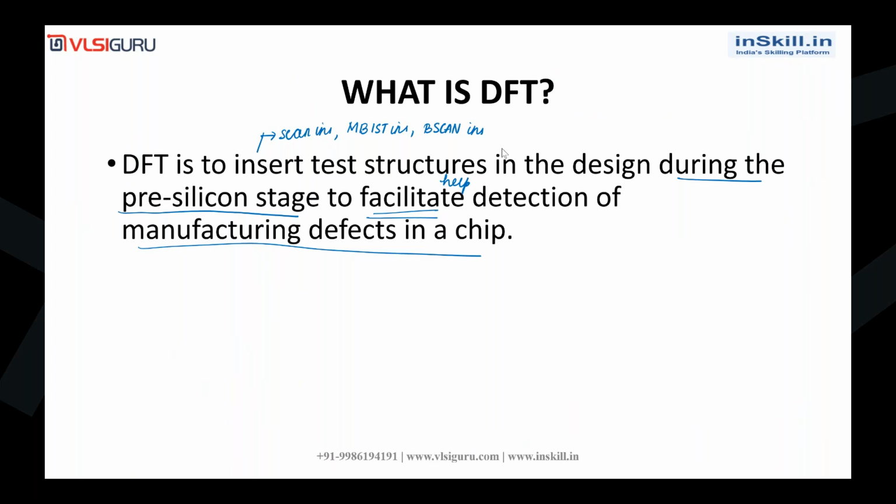So DFT, we will be adding our own test structures in the design like scan insertion, MBIST insertion, boundary scan insertion during the pre-silicon stage. Pre-silicon stage means before manufacturing. To facilitate is to help detection of manufacturing defects in the chip.